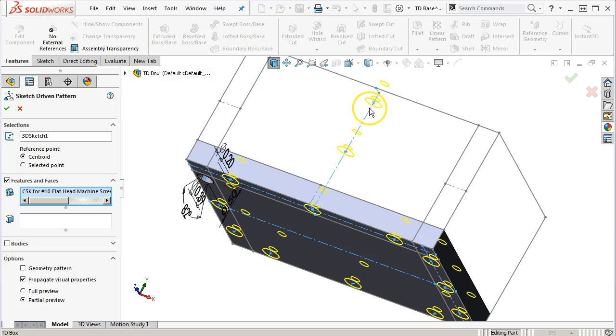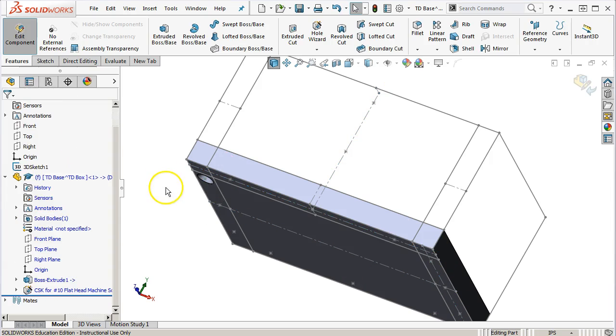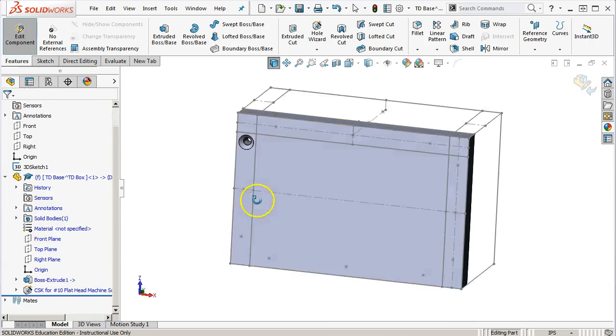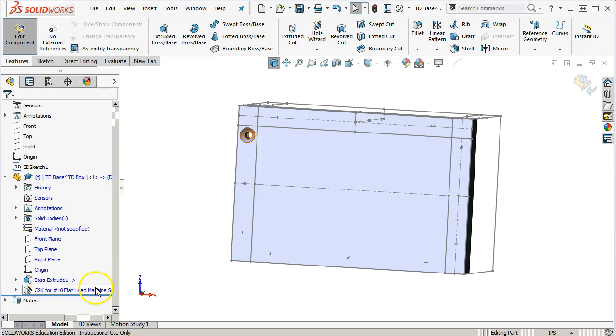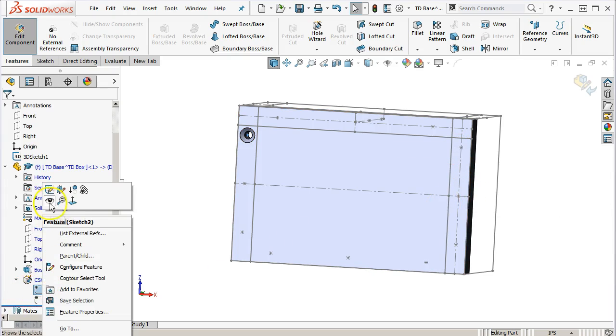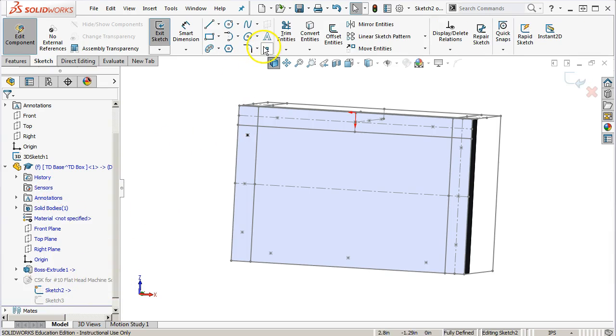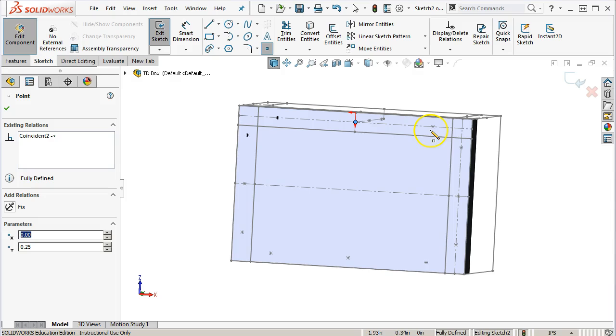Now these are going to fail because they're floating out in space. They can't produce those. Can you delete just those? Not worth it. Okay. I'm going to chase it more than it's going to be worth. If I really wanted this to be a sketch-driven pattern, I would open up a face, create a point, sketch at each of those locations. But by the time I do that, I can go back into Sketch 2, which has the external reference. I can go through and I can do this much quicker. If I need to add one, okay, but this isn't that complicated of a pattern.